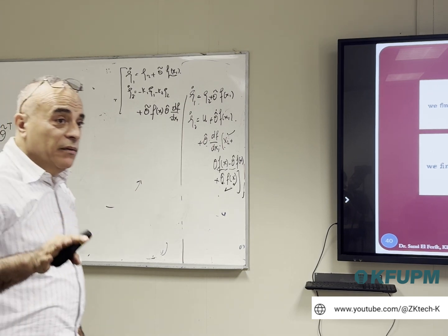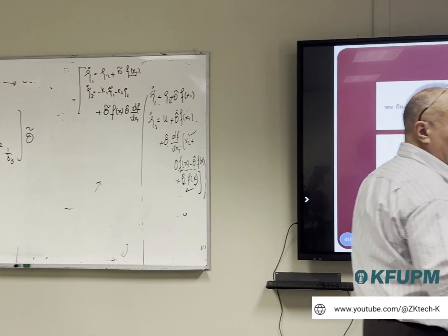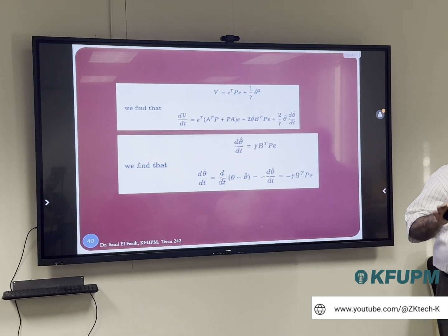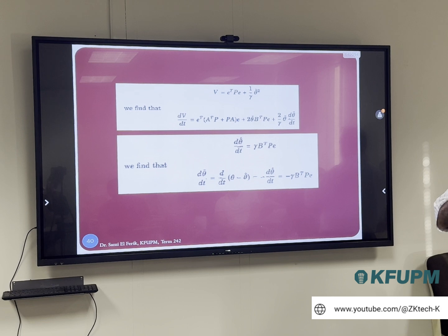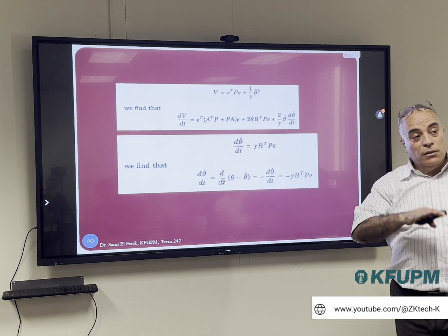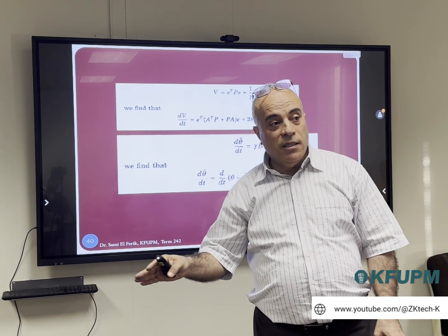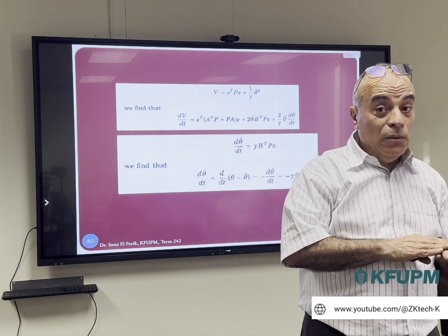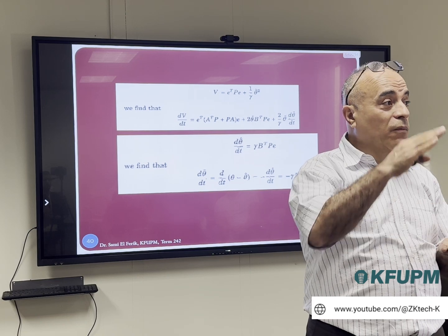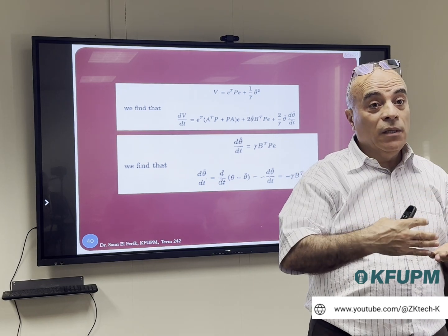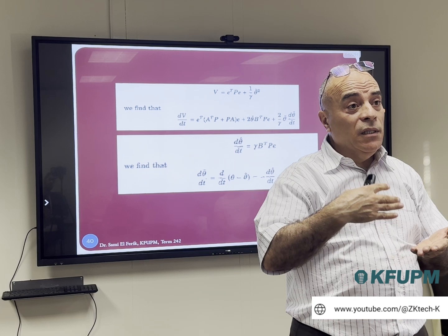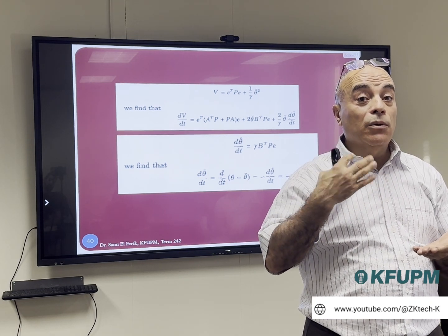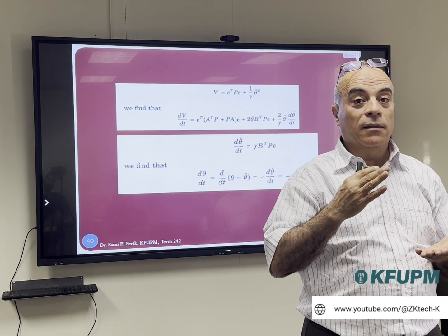It cannot be applied every time. Sometimes we cannot apply it. The system is very complex to apply it. It does not fit the theorem to find the morphism that will allow me to transform it to a linearizable system. Sometimes there are singularities in the controller because of the fact that I have 1 over something divided by 0. And this division by 0 means there are operating points that you should not stay in. You can pass by, but you should not stay in.